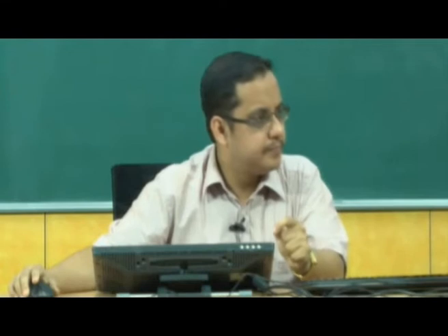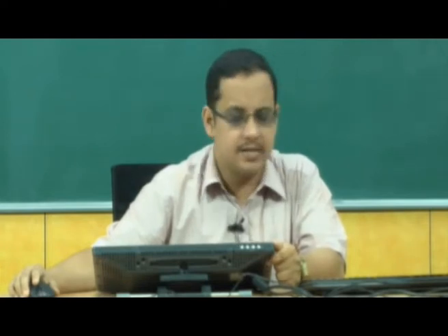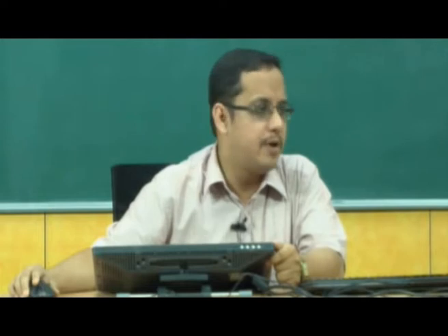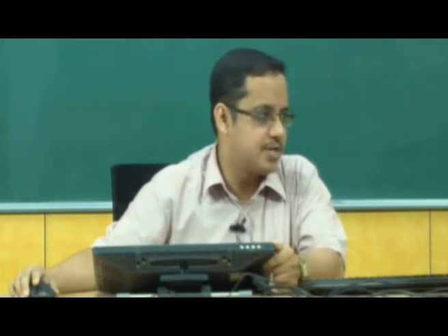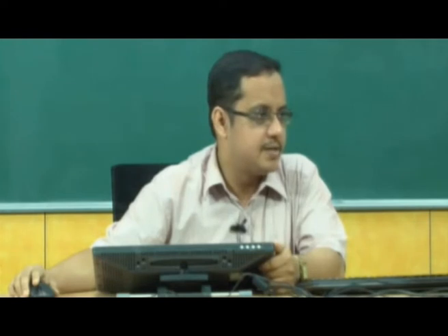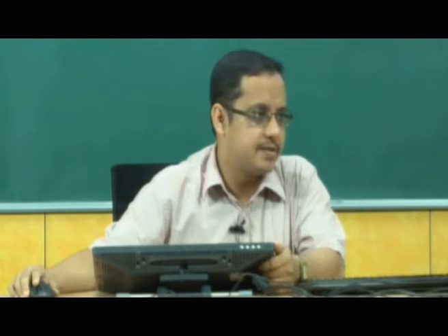Sir, we are from Dwachar. As you have mentioned, balancing is to nullify the unbalanced forces. But in locomotives, we also read that there is partial balancing. Is it correct to say nullify, or is something only reducing the unbalance? What should be the proper definition of balancing? What I said was the objective would be to nullify the forces. But yes, in the case of reciprocating machines, it may not be possible to attain that objective. You will only be able to partially balance it. So that's the answer. The objective is always to nullify, but you may not attain the objective. That's the problem. Okay, sir. Thank you, sir.